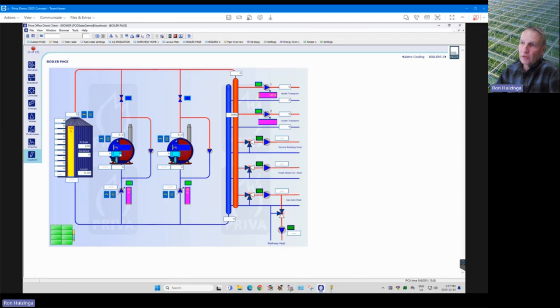So if that boiler gets too cold, the first thing that will happen is this pump will shut off. So that means this colder water coming out of the boiler will loop around like this and keep itself warm. So normally in a system like this, with a boiler loop pump like that, the boiler shouldn't actually get too cold unless something goes wrong, like this pump fails.